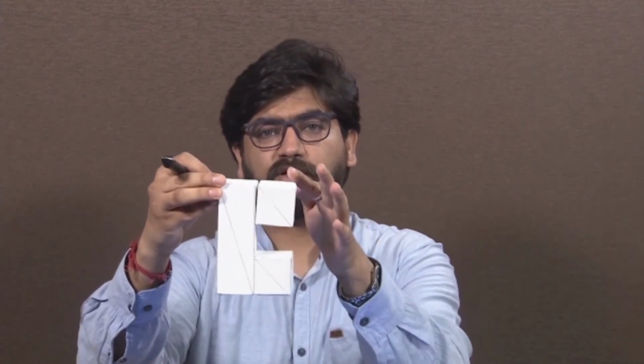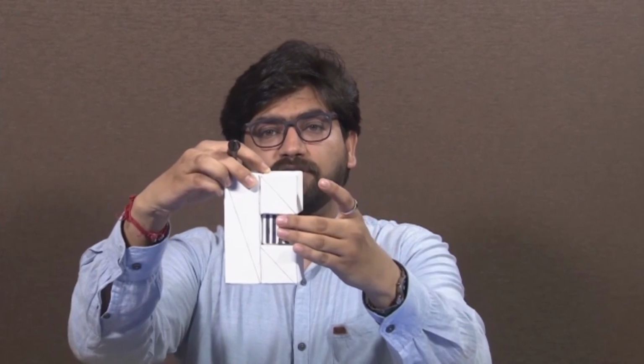Like if I tilt it like this, then this particular part, when we build it, will require some support. To support this particular region, we need to provide some structure that is called a support structure. Later on, when the part is cured, the support can be removed. So this is the basic of support.